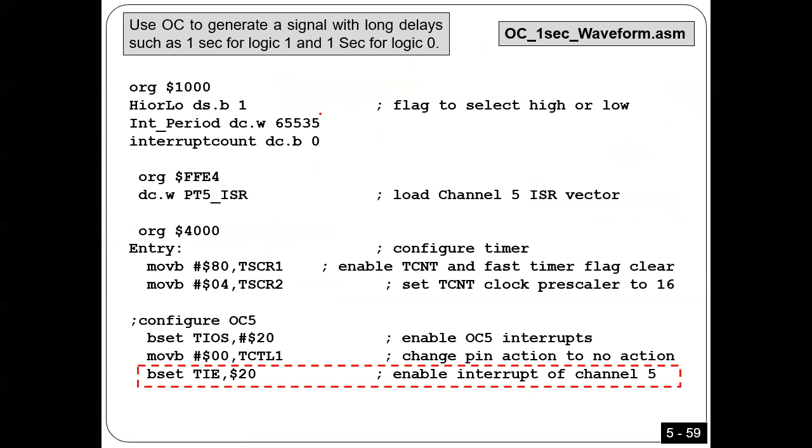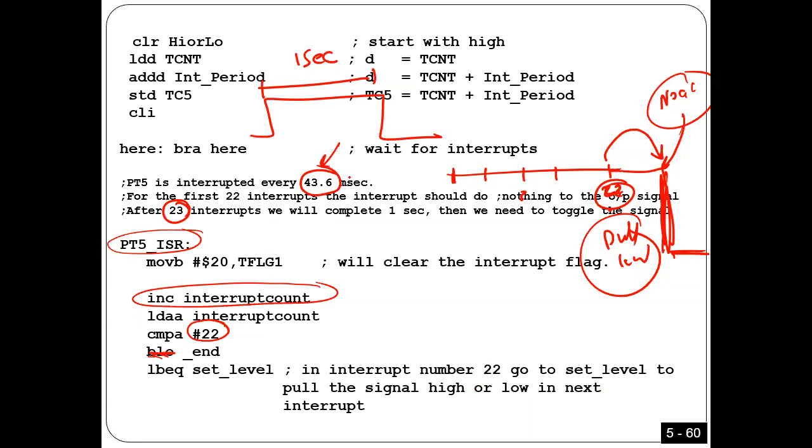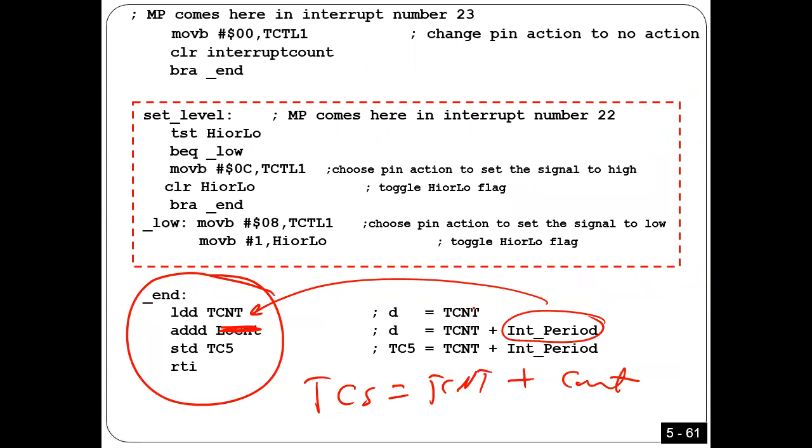Yeah, here. So I'm gonna say make the next interrupt after 43 milliseconds. Is that okay? So here, and then I'm gonna leave. So for all the interrupts from 1 until 22, before 22, that's all what I'm gonna do. In every interrupt, I'm gonna say, please, next interrupt after 43. Okay, and then next interrupt after 43. Okay, this should happen from interrupt 1 until 22.